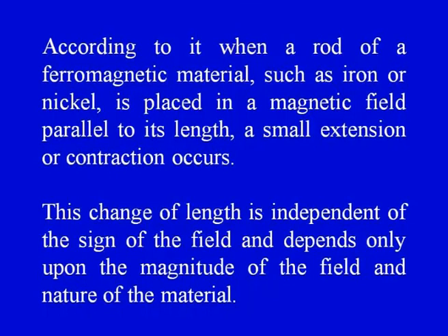When an external magnetic field is applied, these domains within the ferromagnetic material move, rotate, and change their orientation, and the result of these internal changes is that there is a dimensional change in the longitudinal direction, that is along the direction of the magnetic field. As the process is isochoric, there is an opposite change in the orthogonal direction.